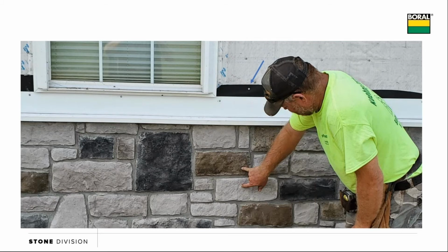But then they went through and put a flashing on. This flashing is required anytime we transition between 2 dissimilar materials. We need a horizontal flashing there to take any of the water from above and dump it out so it doesn't get back in behind the cladding below. But unfortunately, they nailed that flashing on top of the 2 layers of paper. It's called reverse flashed. Now, if any water gets in behind our cladding above, it's going to travel down, and I guarantee it's not going to jump off the white paper onto the black and then onto the flashing. It's going to get driven behind the stone, and in 3, 5, 7 years, when the OSB or plywood behind there is deteriorating and the mason gets called, that's what we'll find was the issue.